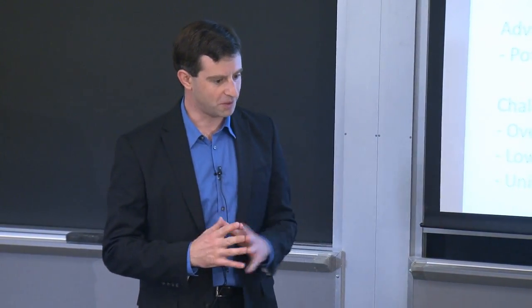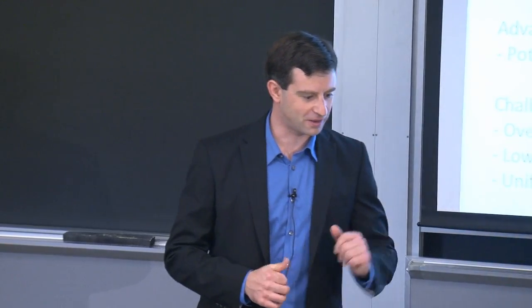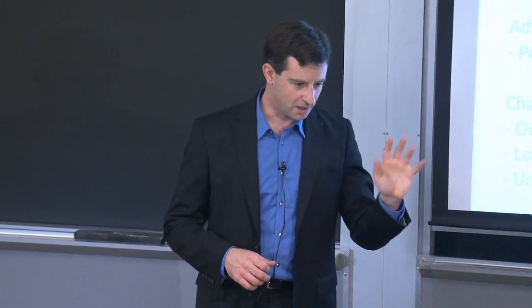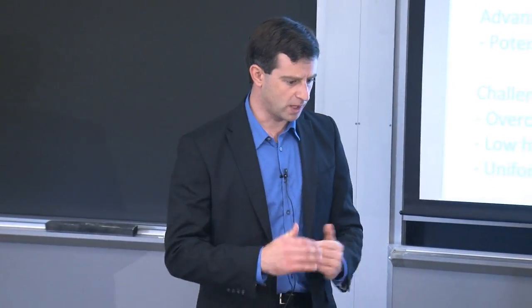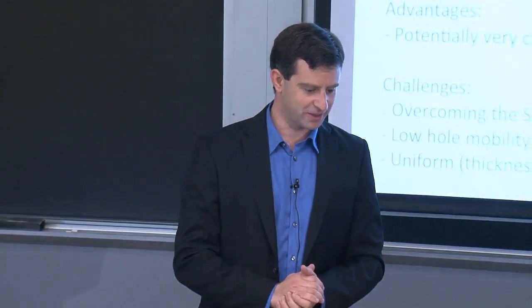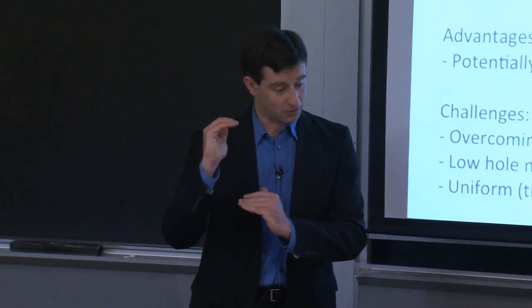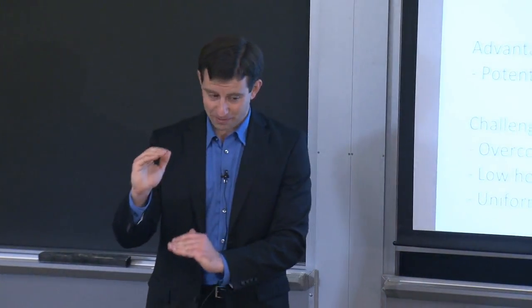And I have heard of amorphous silicon materials that have gone as low as 10 to the minus 4 centimeters squared per volt second and as high as approaching 1. So we have a range of material qualities as a result, and also a range of performance. Likewise, there's a range of stress in the film, depending on how you deposit your amorphous silicon.